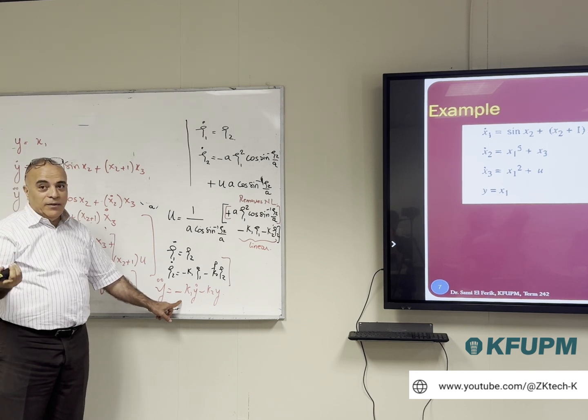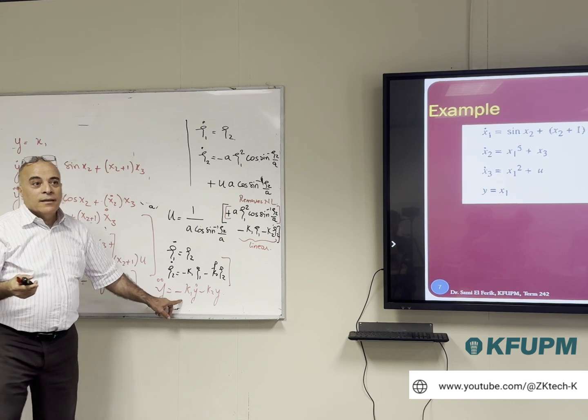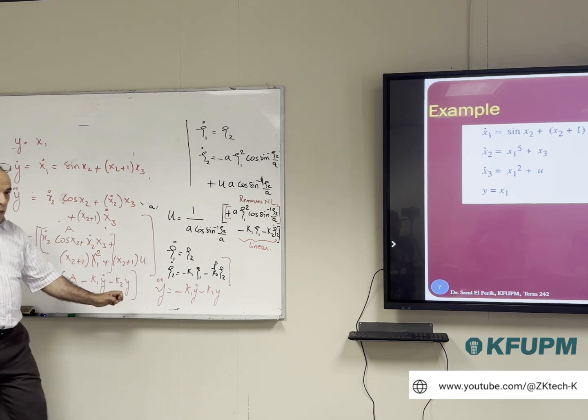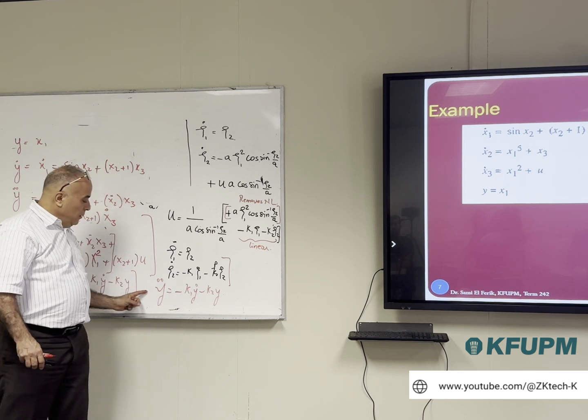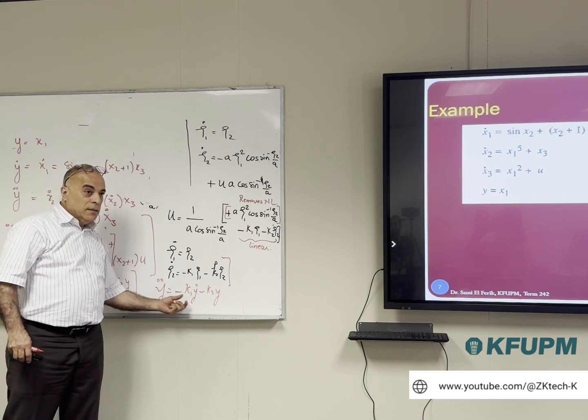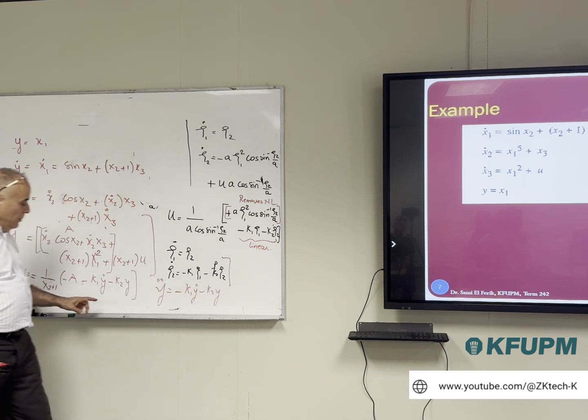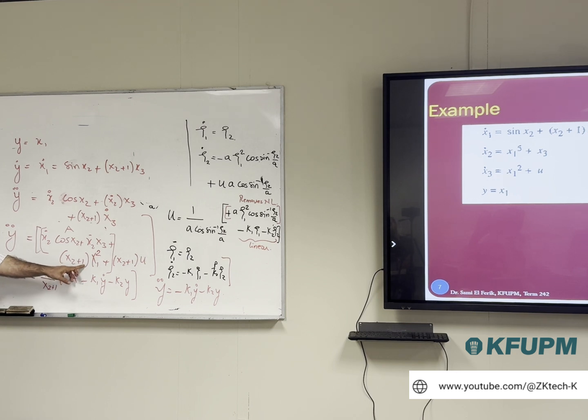You saw it in the midterm, you were supposed to have revised it. So Routh-Hurwitz is saying that all the parameters of the characteristic equation should not be 0. This is the necessary condition, and they should be of the same sign. So since I have the second derivative here, and I cancel all this term, the term that I need to add should be linear in y prime, because this will multiply s, and in the value of y. And this will go to 0, stable. And this will be my controller u that will cancel all these terms. Everybody is okay with this?